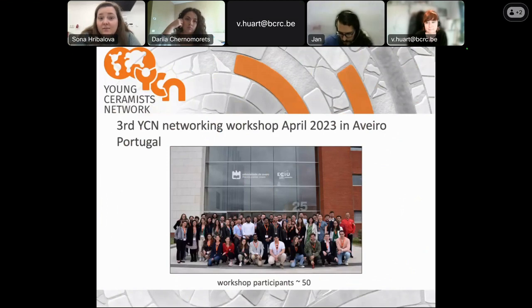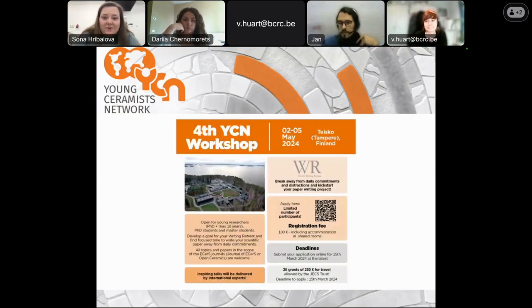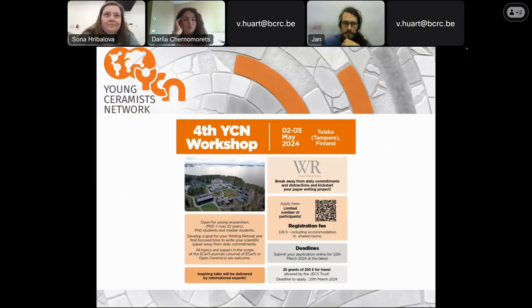Because if you have material that's translucent, which is here the, let's say, black part with the black border, that's alumina, and it is translucent. If you place it directly on the paper, you can see quite nicely through it. Once you lift it up, everything gets blurry. Why? Well, because you have scattering. And the same happens down here. If we have two similar samples, one that has quite a lot of porosity and the other that doesn't, you actually can see the difference, and that's just by scattering of light.